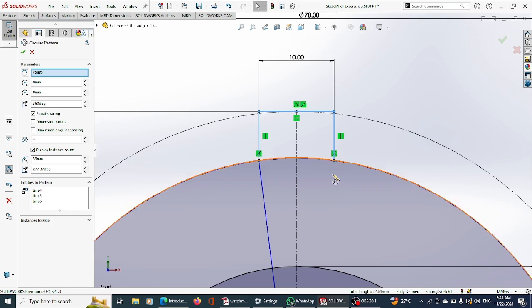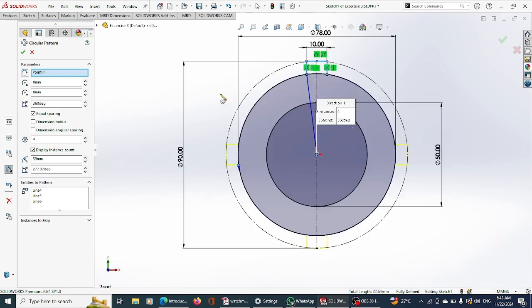After doing that, let me use the key F and come. Good. You're already seeing that there are four previews. It has not been entered though. This is just showing you how it's going to look by the time you press enter. So come to the menu where you can change things. Let me quickly show you something. Some people, when they click circular sketch pattern, it does not appear automatically like this, and it will appear in a very funny way.